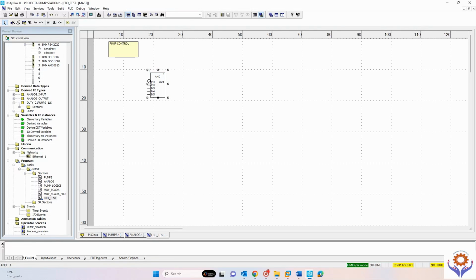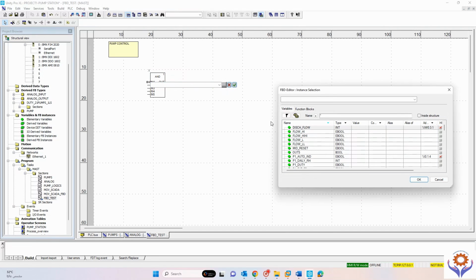See here, I am just going to browse the existing IO which we used in the earlier class. See here, I am going to use pump, not pump mode, pump. I need pump auto, no? So I will search for pump auto. See here, I have many IOs. If you click the address format, you can find the IOs. See here: pump run, pump trip, moisture, temperature, pump auto.